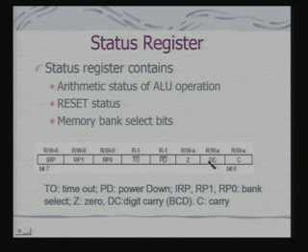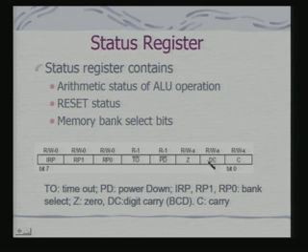Why is that carry important? If I am looking at BCD operations, in a BCD operation, I need to keep track of the carry from the 4th bit, and that is why I have got a special status bit to indicate that. These 2 bits are used for timeout indication as well as power down mode, and these we shall discuss when we consider the power management aspect of these microcontrollers. These bits are used for memory bank select.